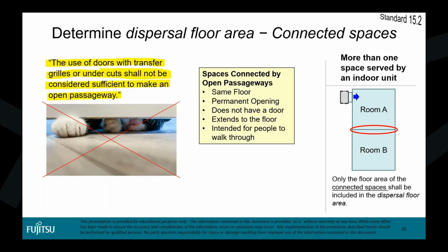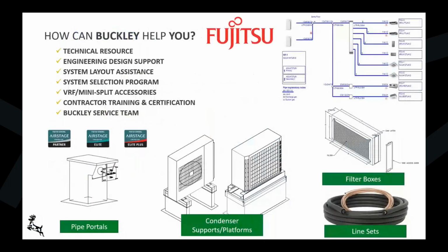Great. So if you have any other questions, please feel free to throw them in now. Richard, are you still on the line? I am. There's a new question that came in. It asks, does ASHRAE 15 limit the use of copper line sets? No, it doesn't. It's specified there in several pages, and compared to the previous standard 15, it is a little easier now. You specify what kind of copper and sizes, but no, there's no limit.